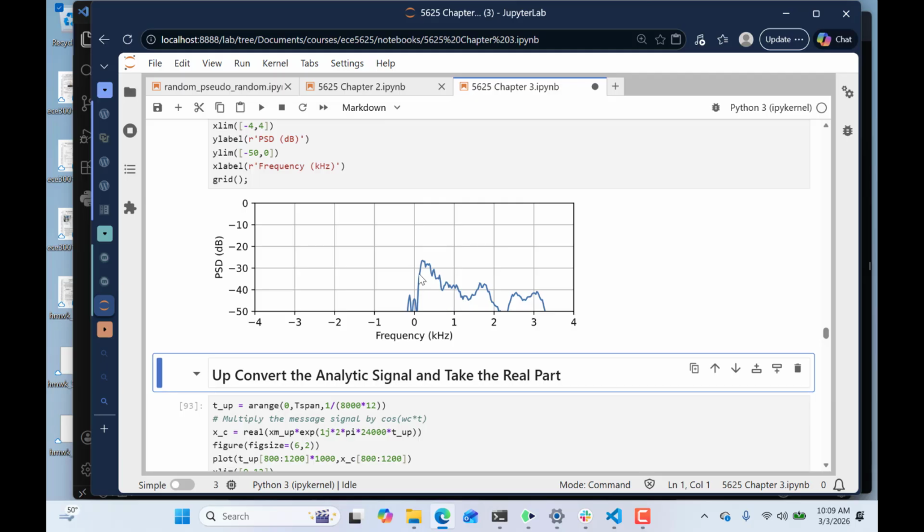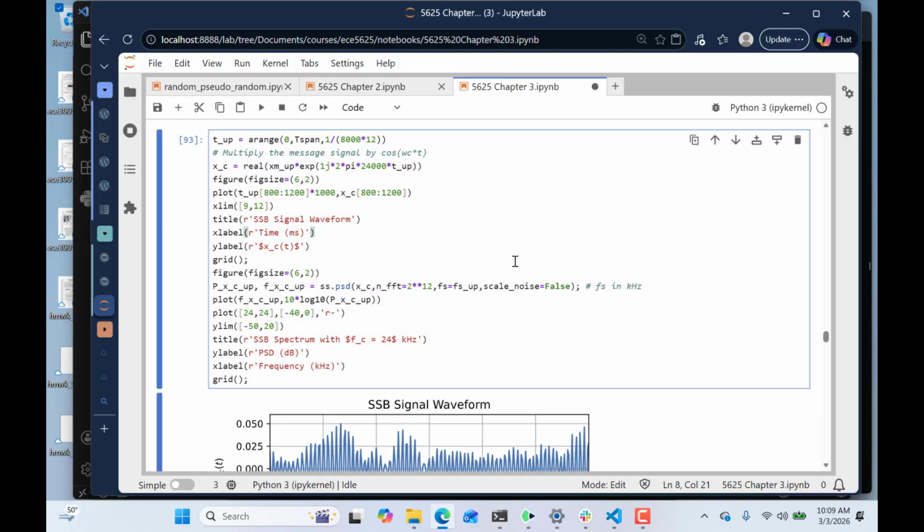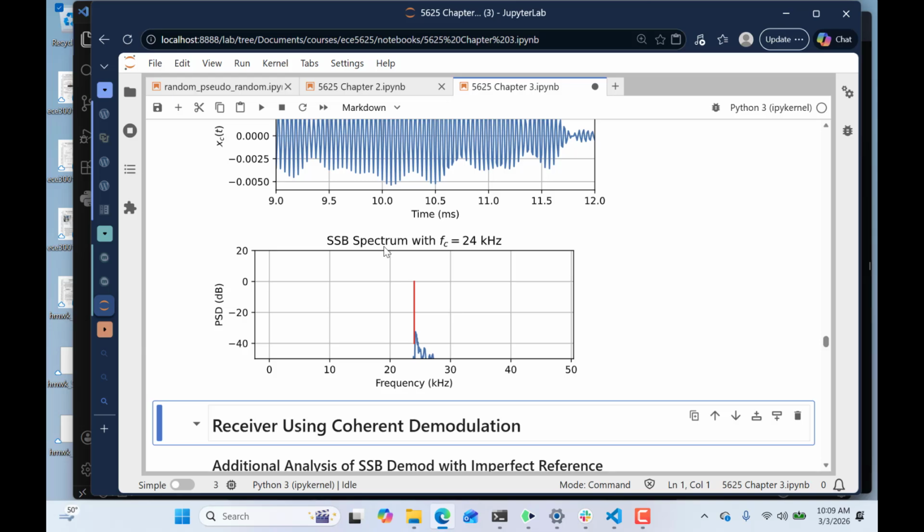and there it is, at baseband. So it's the upper sideband, and there's no mirror image. So this is now a complex, or analytic, signal. I will upconvert it to 24K, and 24 kilosamples per second is the carrier, and there's its envelope. I just put a little tick mark on here to show that 24 is right here. There's a little bit of slop over because the filter doesn't pass DC, but it does pass a little bit of the negative frequency. So for all practical purposes, it's pretty clean upper sideband. Agreed? You don't see the mirror image down there anymore.